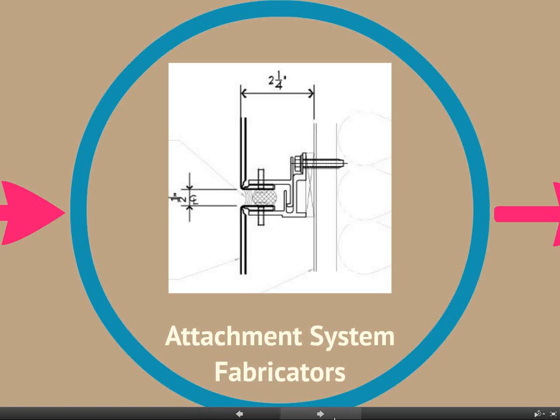that, as is shown here, they're usually extruded systems. And you'll notice that this detail, which I took just this week from one of the major manufacturers of the panels, does not show continuous insulation. It shows the system being mounted directly to sheathing. And of course, if you're just doing an entrance canopy or something like that that's not conditioned, and you may not even have any insulation at all, you can get away with that. But now that we have the requirement for continuous insulation, this won't work anymore.